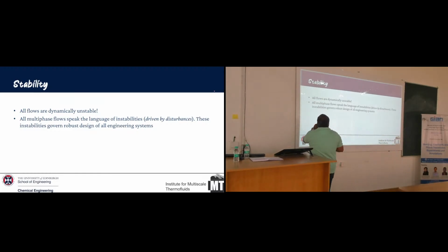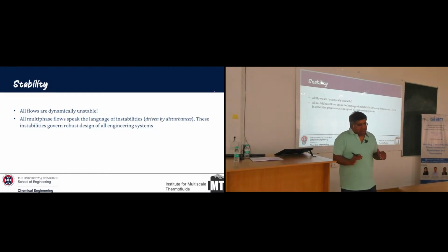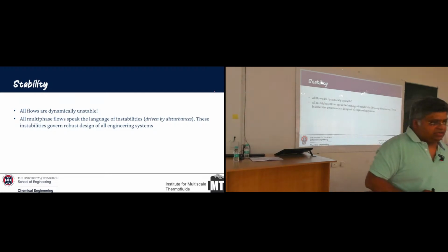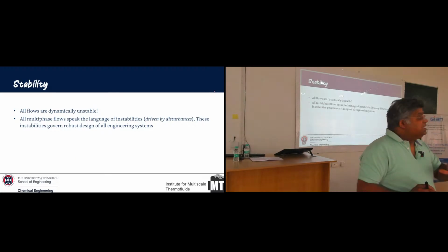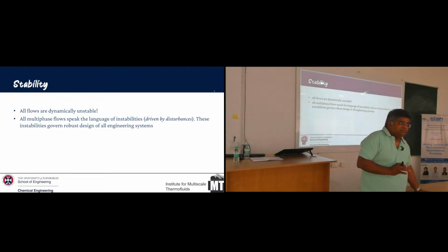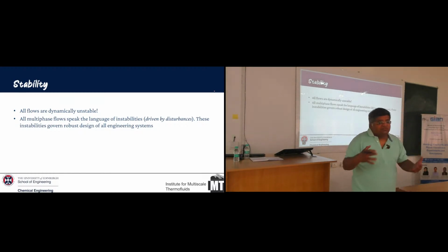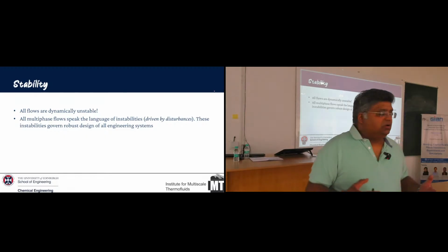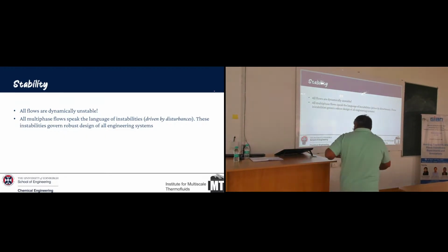Okay? Now, the thing is, all flows are unstable. And the reason they are unstable is because there are some inherent instabilities. Typically, the most important instability that happens even without our notice is the surface roughness. The surface roughness causes something called the Tollmien-Schlichting instability. I'm going to show you.